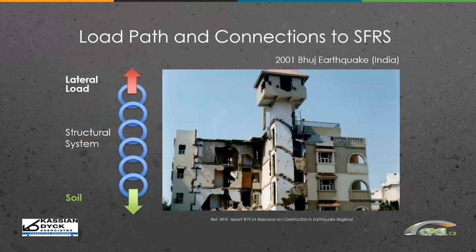We mentioned earlier that the diaphragm is just one component of following the force path through from the point of application of load down through the structure into the soil and foundations. Basically it's an integral part. We have to ensure that the structure performs well, the diaphragm performs well, the connections perform well. Obviously this is not a precast structure, but if we have failures during a seismic event and we lose part of the structure due to one link not being strong enough within our load path, then it doesn't do much good if certain parts remain and certain parts of the structure fail.